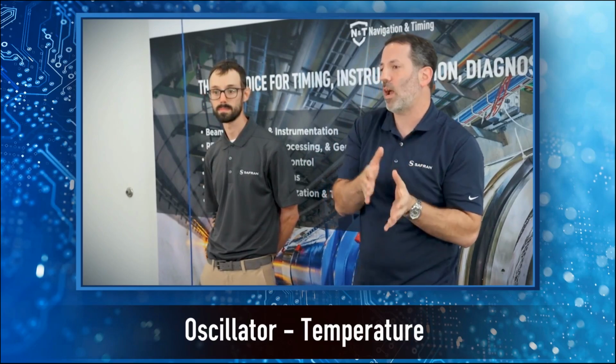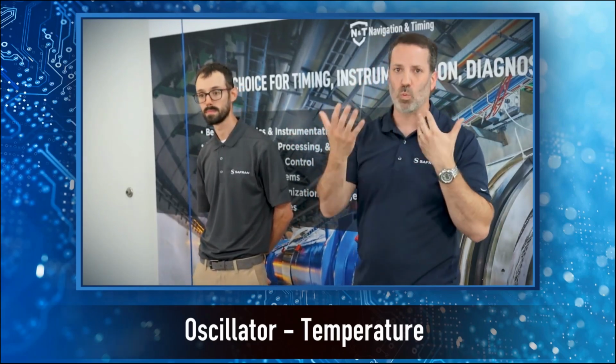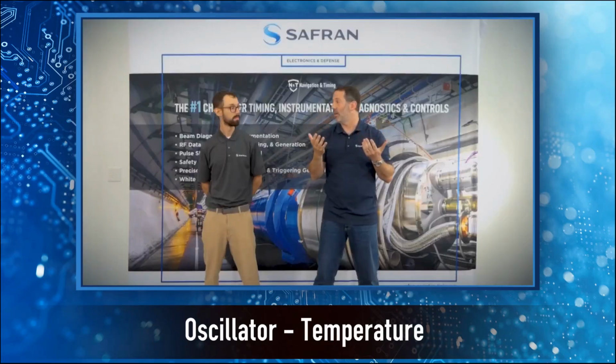The other piece that really comes into play is temperature. Temperature is really the biggest environmental effect on these oscillators. And as you get into our higher quality oscillators, they're less impacted by temperature. Now, while you're synchronizing, that's not a big deal, because part of that synchronization will account for those temperature effects that are happening during the day.